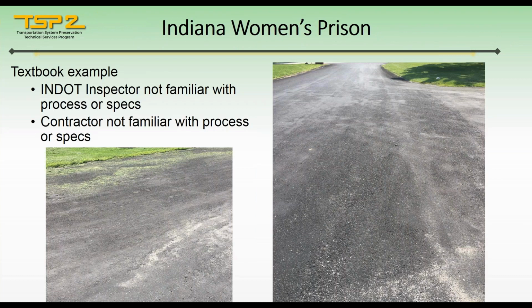So to kind of tie together what Neil was talking about, the importance of having the certification for both the contractor and the agency. We did a contract, it's been a couple years ago now, at the Indiana Women's Prison west of Indianapolis. This was a service road and parking lot going around the prison where we contracted the chip seal. Something that we learned right off the bat, forget quality, is chip seals are not necessarily a good choice for parking lots. You've got too many turning movements, you've got people walking around, just not a good application for